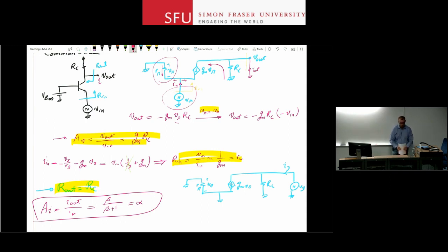But in general, a small signal analysis will get you to the right result if you do it right. And I actually strongly recommend you to do a few small signal problems first, then come back and use these formulas for the analysis of the circuit. And in that case, we draw the AC circuit, which is basically the same circuit as the large signal, with all the capacitors shorted, all the DC sources removed, and we use the knowledge that we have about the basic stages to solve those circuits.